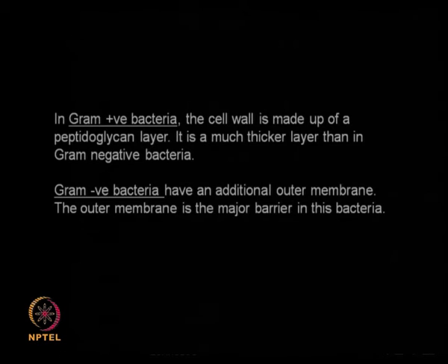It is a thick layer when compared to the gram negative, correct, whereas gram negative has an additional outer membrane, and this outer membrane is the major barrier in this bacteria. Okay, so there is a difference between gram positive and gram negative bacteria, and that difference you need to consider if you are going to select your breakage equipment, whether my organism is a gram positive or a gram negative.